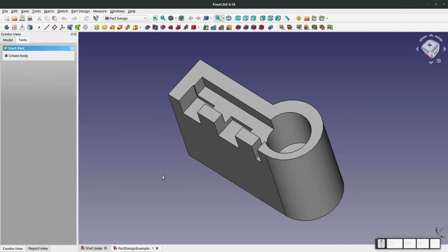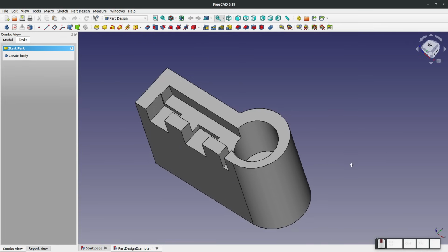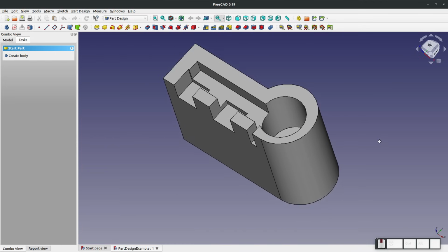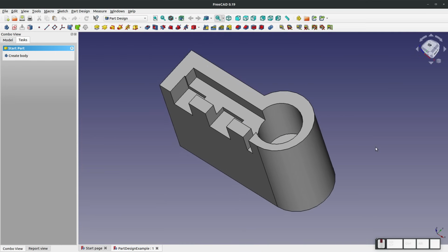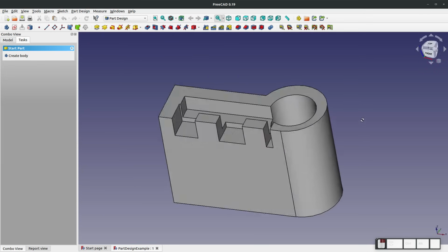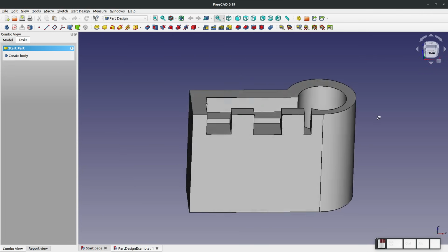How do we adjust our views when looking at a part? Well, here I've got a keyboard monitor so you can see all of the hotkeys that I use as well as how I click my mouse. So keep an eye down here if you get confused on how I use my keyboard or mouse. I can pan my view up and down by using the center mouse button. I can roll my view by using the center mouse button and simultaneously right-clicking. So I can roll my view around.